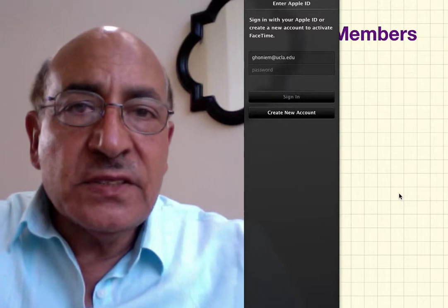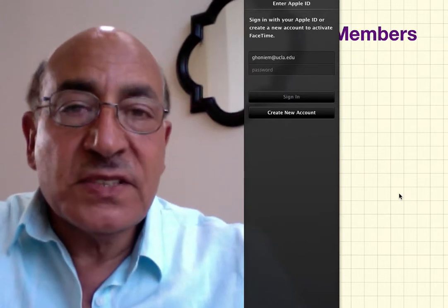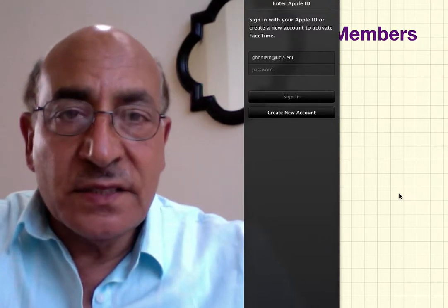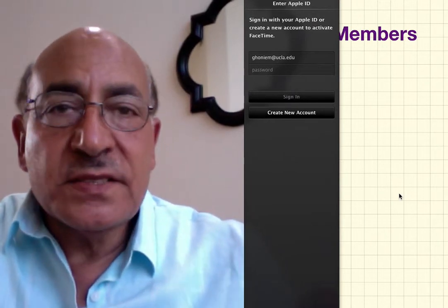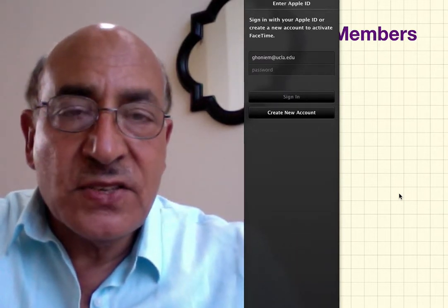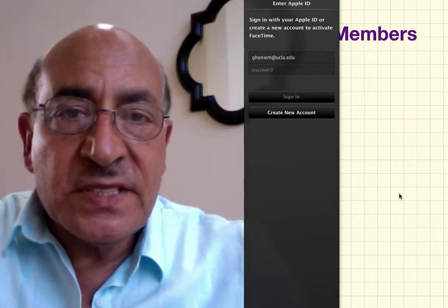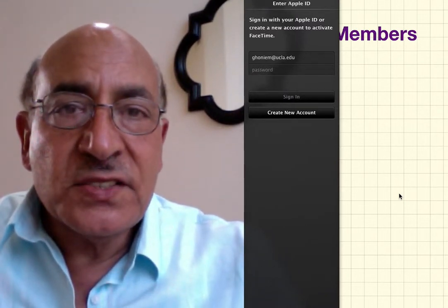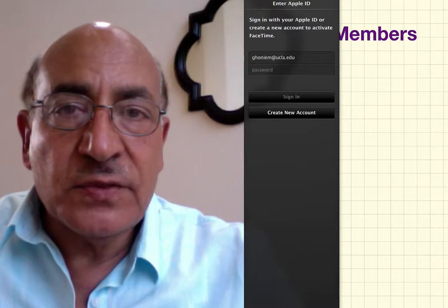And finally, a strut is a member that is usually, as a matter of fact, always in compression, and it is more slender than a column. In other words, it doesn't have the same thickness as a column, and it could be at some inclined angles, such as in trusses, where you have some members that we can call struts. So that's the subject that we will discuss today in a variety of applications, and we want to determine the critical conditions under which such members would undergo buckling deformation.